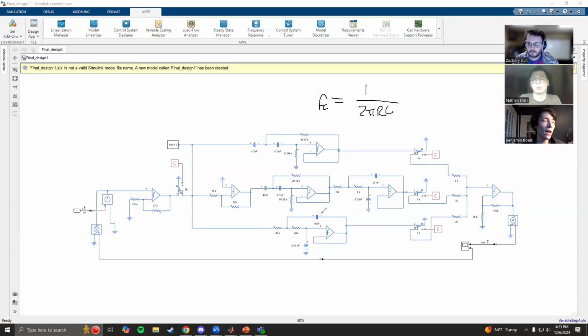because of the overlap between those and the band pass filter, you get a big boost in the frequency response near the cutoff frequencies. So you get a less flat frequency response when all the filters are letting everything through.